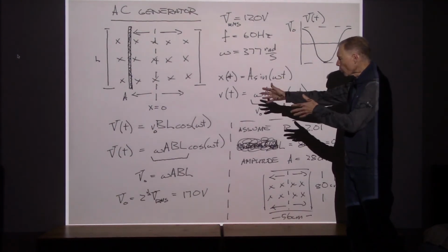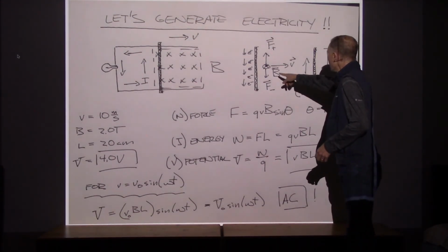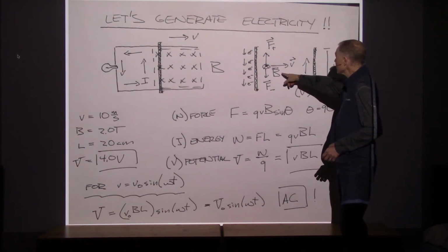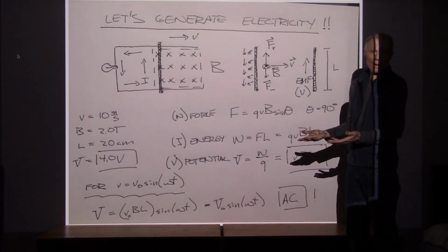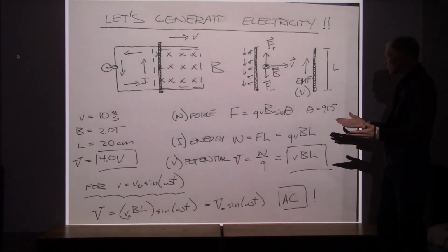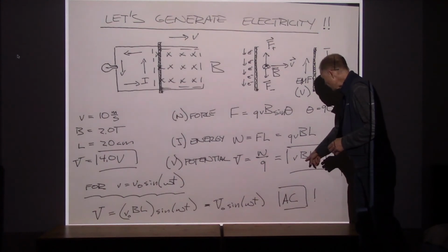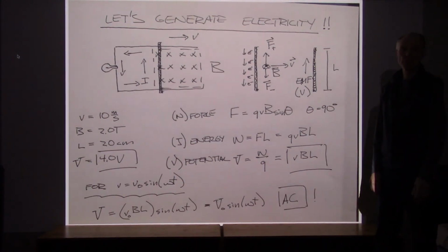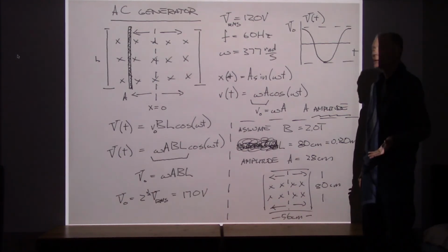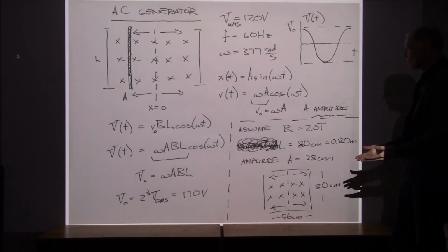Now, there are some formulas that we've worked through here showing the magnetic forces that come into play whenever we move a conductor through a magnetic field. Those magnetic forces are going to generate currents. They're going to generate EMFs. So the first step was to determine how much voltage we are going to get. In general, any conducting material moving through a magnetic field, whatever length is passing through the field, times the field strength, times the velocity, gives us the voltage or the EMF for that generator. We can now hook that generator up to any kind of circuit, and it's going to behave the same as a battery would. So this provides us an alternate EMF source.